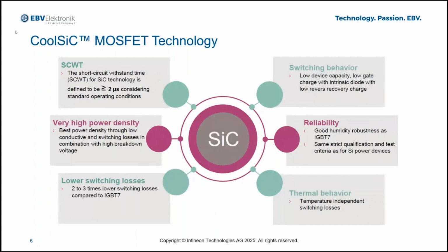Now let's move on to give an overview of the CoolSiC MOSFET technology, which is the brand name of the silicon carbide technology from Infineon. Here also are some interesting, relevant features for motor drives. Silicon carbide is actually a good technology to drive motors. Infineon specifies on certain families of devices and in modules a short circuit withstand time defined to be at least 2 microseconds, considering again standard operating conditions.